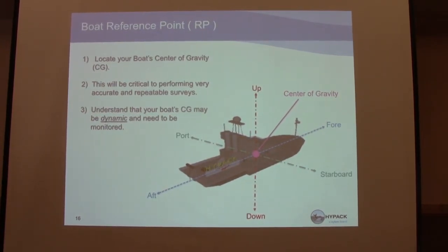So people ask us all the time, can I just offset everything to my sonar? Well, you can if the RTK antenna is on the same pole and the MRU, the heave sensor, is on the same pole. However, the takeoff angles are more accurately computed when everything is offset to the center of the boat, because that's the way our programmer wrote the program. Okay, so very important thing. So sound velocity and finding the COG of the boat for your offsets.